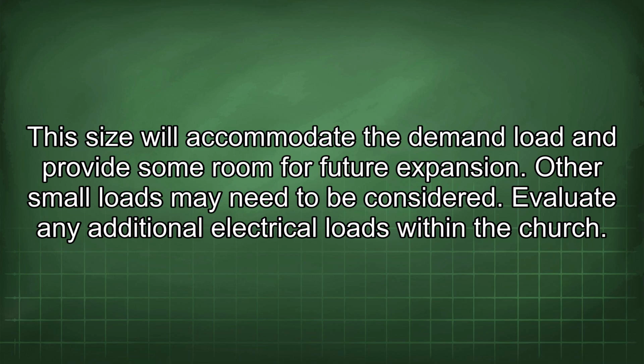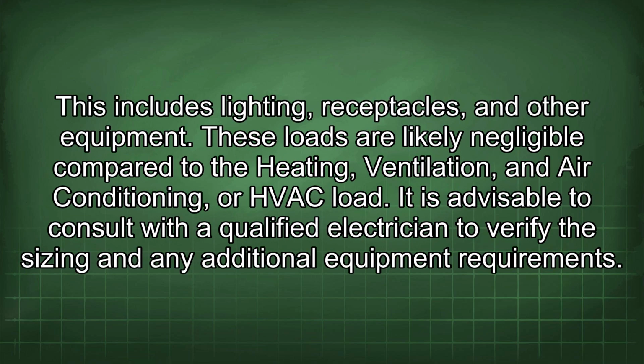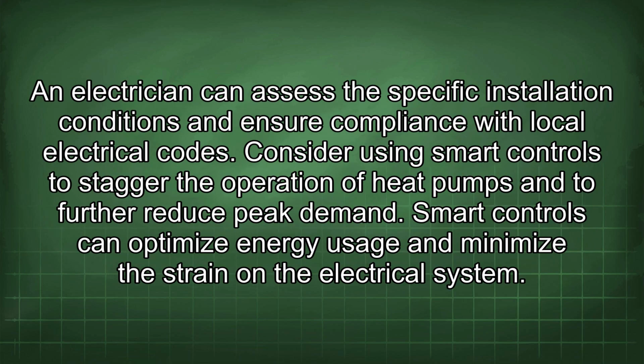Other small loads may need to be considered. Evaluate any additional electrical loads within the church. This includes lighting, receptacles, and other equipment. These loads are likely negligible compared to the heating, ventilation, and air conditioning, or HVAC load. It is advisable to consult with a qualified electrician to verify the sizing and any additional equipment requirements. An electrician can assess the specific installation conditions and ensure compliance with local electrical codes.